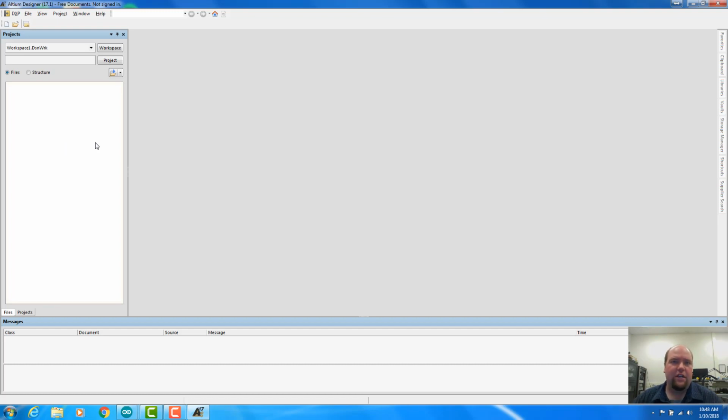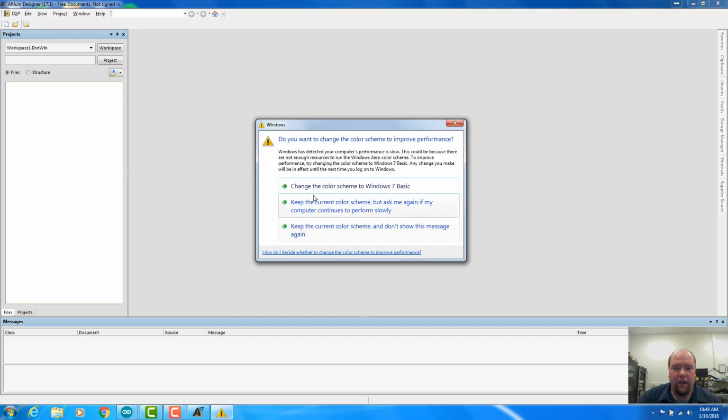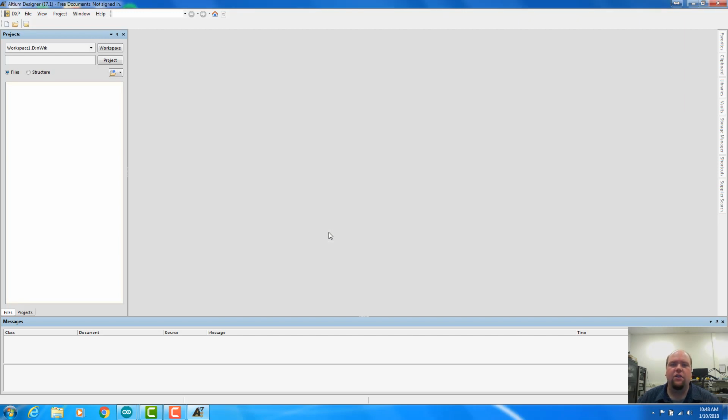So the part that I want to do today, you'll see a lot of tutorials that are just, here's an 8-pin DIP package and we're going to make a footprint for it. That's kind of boring. I'm going to talk about what happens when your footprint's a little bit different, how to make a footprint that's got something a little bit weird or wonky about it, maybe something that's a little bit out of the ordinary. So today we're going to do a part that has an uneven pin spacing and a part that has a thermal pad. So both of those things come up a lot, and it's good to know how to create a new part for something that's a little bit stranger than the standard component.